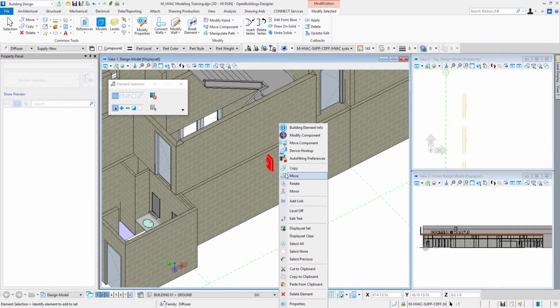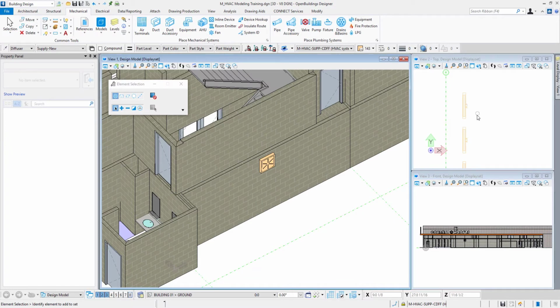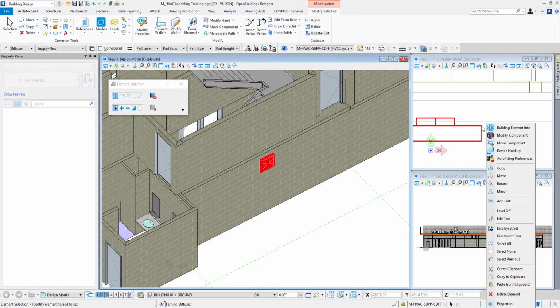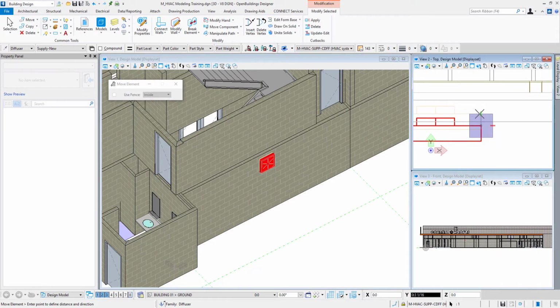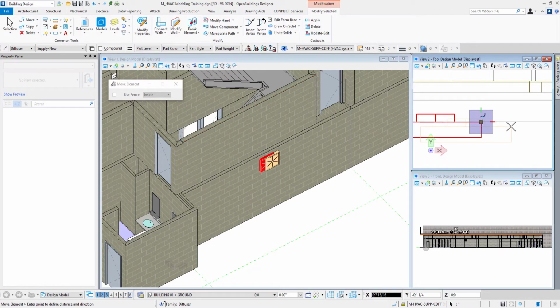Again, with my right press on my mouse, I'll select rotate. I want this one to go 270 and about element center. So I'll left click to accept it, or right click to end that operation. Come back over here to my top view and take a look at it. I'll move it into the wall. So what I'll do is choose this corner, move, select my start point for my move, using AccuDraw, pressing N to lock, to set my snap mode to nearest, and then a right click.